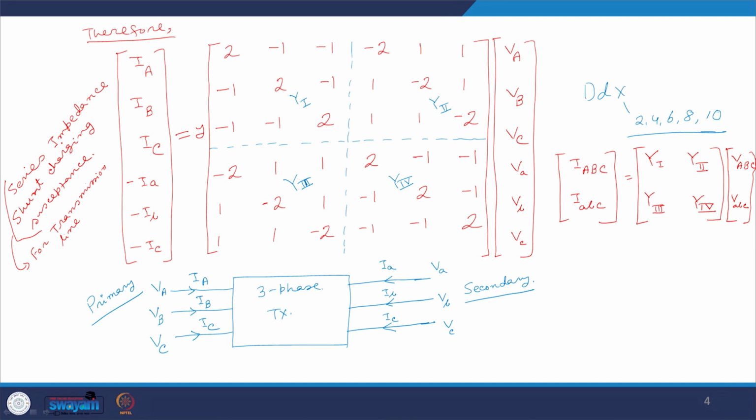And as we do in the case of a balanced transmission line, we will represent every three-phase transmission line by its equivalent pi model, where the series part would be represented by its series impedance matrix, and the shunt part at both the sides would be represented by half of the shunt charging susceptance matrix. So it would be an equivalent pi model of a transmission line.